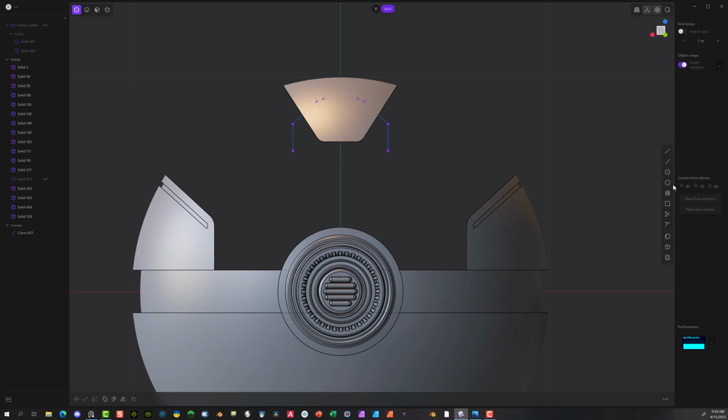I think I'm also going to do another square here. So we're going to bring this up, kind of center that. Say OK. Hit these two points. Go ahead and hit the S key. Scale this up a little bit just to give it some variations. Say OK. Alright, so that's good. So we're going to go back to the object tool. We're going to select this. We're going to hit the cutter tool. We're going to go ahead and cut that through.